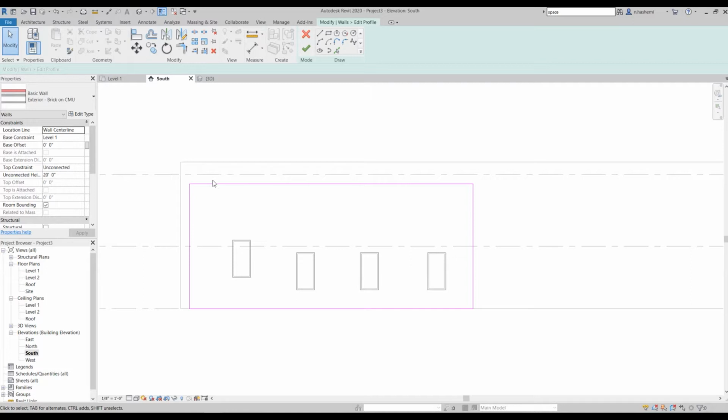Now let's make, for example, this corner chamfered and make a strange shape out of this wall. So I'm going to use the Spline tool over here to draw a curved line. Okay, I'm going to have a curved line over here. I'm going to just draw a curved line, and then I need to trim the shape. So I'm trimming these corners, and then I'm going to chamfer this corner. Okay, and then right now let's create some holes and openings in our wall.